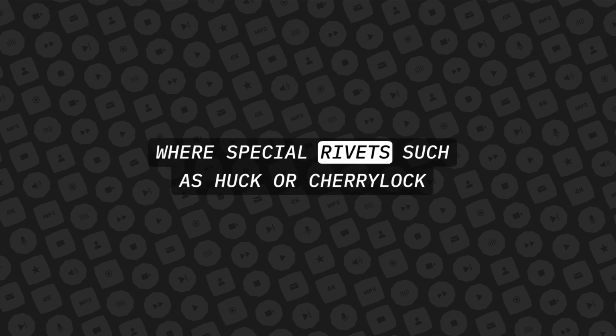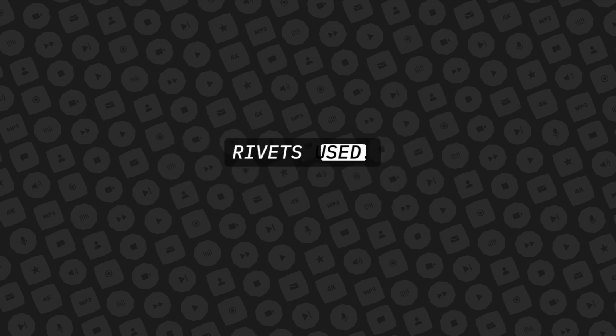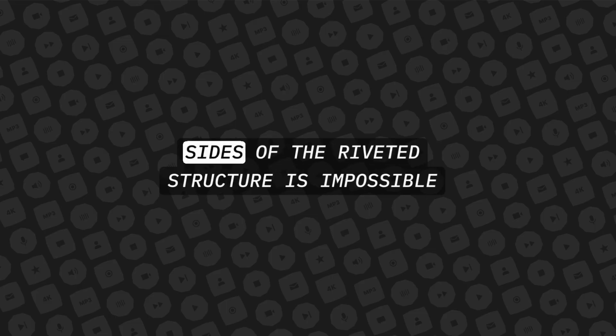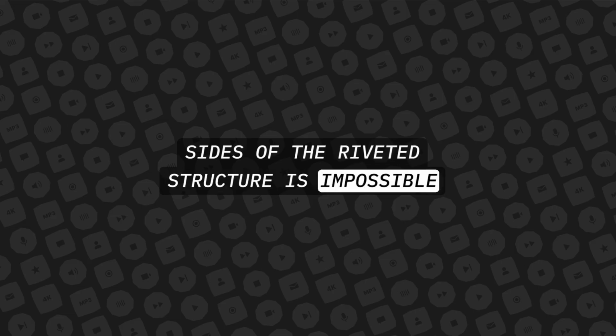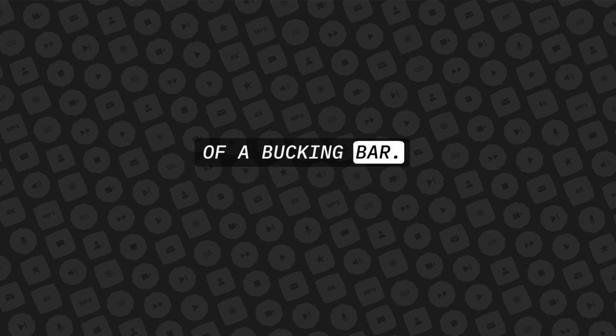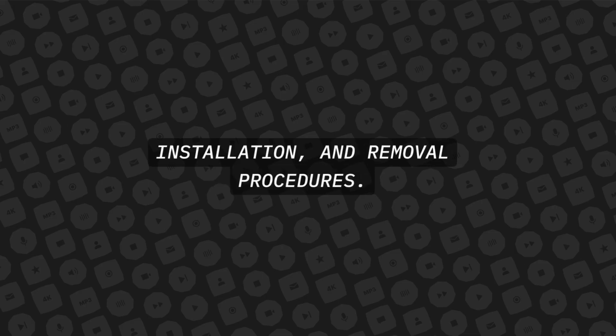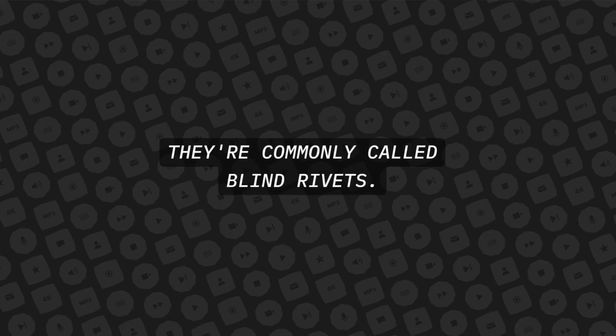Where are special rivets such as huck or cherry lock rivets used? They are used in places where access to both sides of the riveted structure is impossible, or where limited space will not permit the use of a bucking bar. These rivets require special tools, installation, and removal procedures. They are commonly called blind rivets.